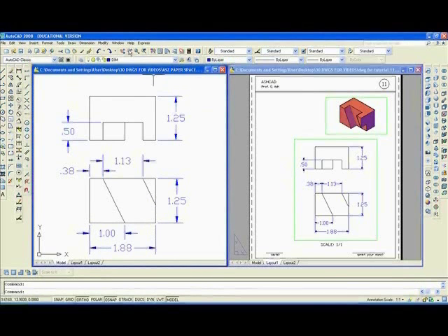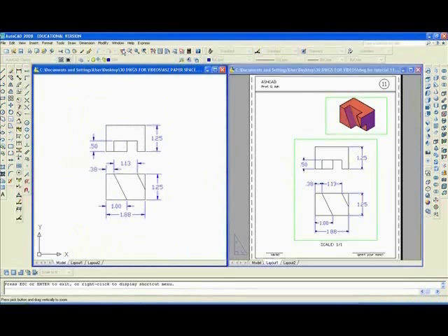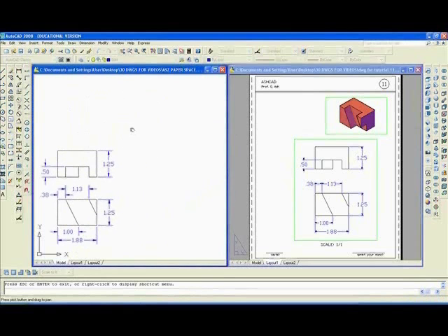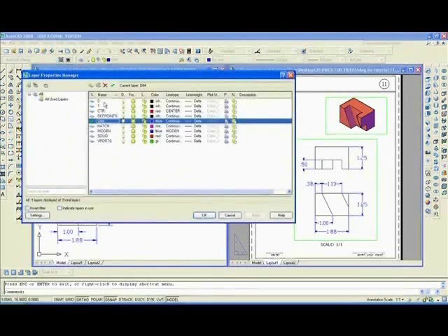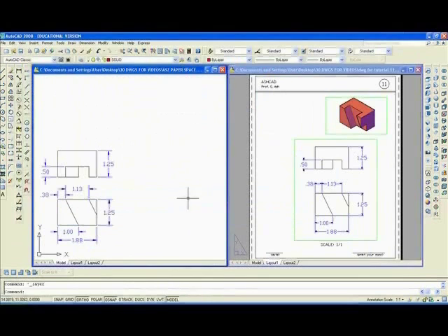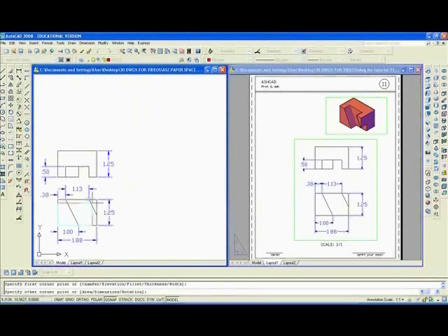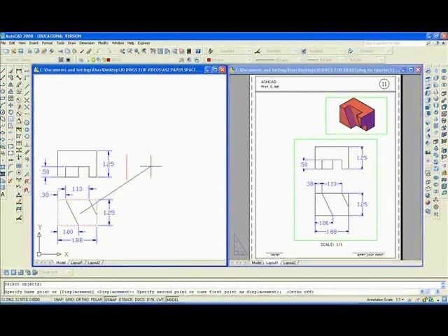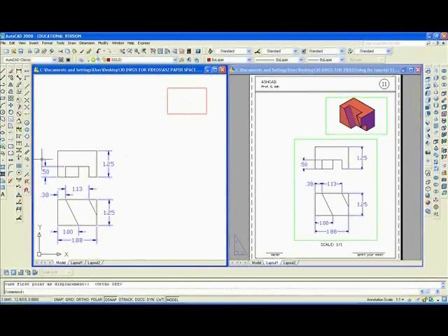First thing I'll do is to zoom it down, pan, move that over to that side of the screen. Change the layer to solid current. Use a polyline. Well, better still, I'll use a rectangle right now. Pick 2 diagonal points. M, enter, L, enter. Move the last object I made and take ortho off. Move it to the upper right.